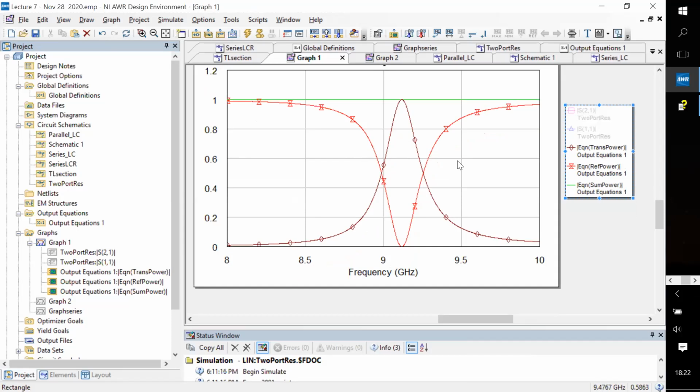This is actually a transmission line, so the response is not symmetric on the left and the right. Even if you look carefully here, this is not really symmetric, but the same asymmetry will be present in either the transmitted or the reflected correspondingly, and they have to add up to 1. So that will always happen. Yes. I was talking about the asymmetry in the peaks, in the transmitted and the... Yeah.